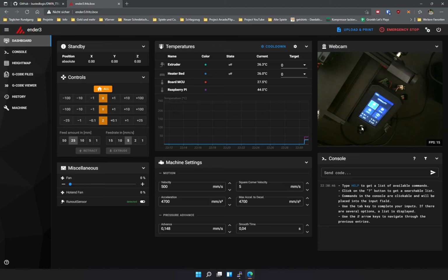Now it's done. You installed Mainsail, you just set up your printer and installed the dwin files for a working display on the Ender3 S1. As you can see down below, there is the Raspberry Pi set up with the GPIO ports. On the right side I have an additional RJ45 jack, which I used for my ADXL345, and this can run simultaneously and parallel to the display, as it is plugged into ports that are not used.